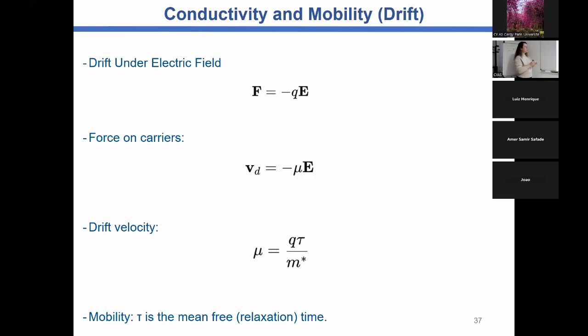experiments. Using space charge limited current, which means that we will have some block current and measure the charge that can be transported. But we can also use the Hall effect to measure this mobility. And the mobility, as I told, is quite different if we have a semiconductor with N-type, P-type, majority type holes or electrons, and between the holes and electrons it is also different.